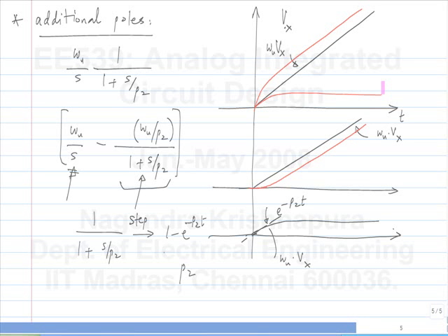So the analogy is, let's say you are again driving a car and your aim is to stabilize the speed of the car, but the speedometer gives you the speed, not the speed now, but maybe from 3 seconds before. So what happens? You will overcorrect, and then you have to overcorrect on the other side, and so on. So if you have delay in a feedback loop, you can intuitively figure out that you can get into oscillations, right?